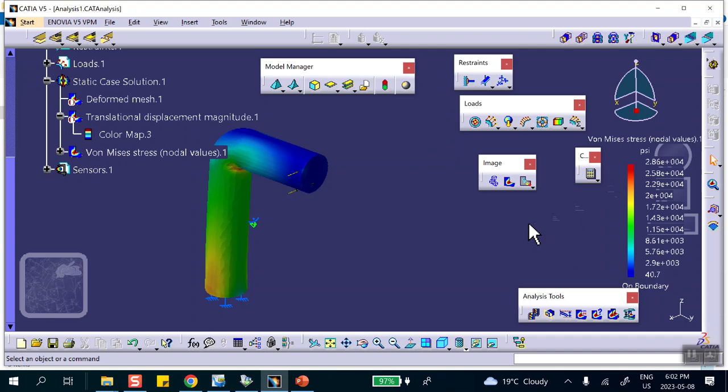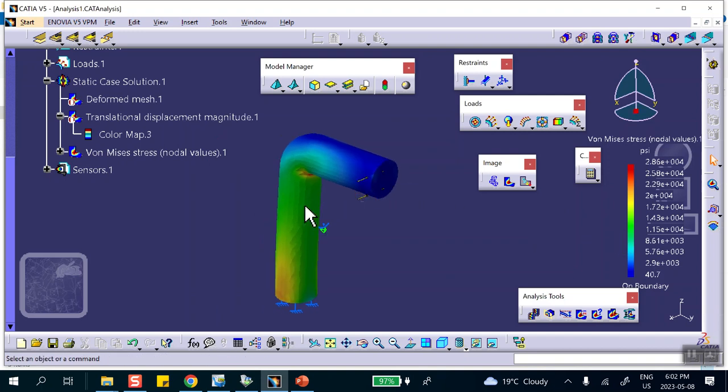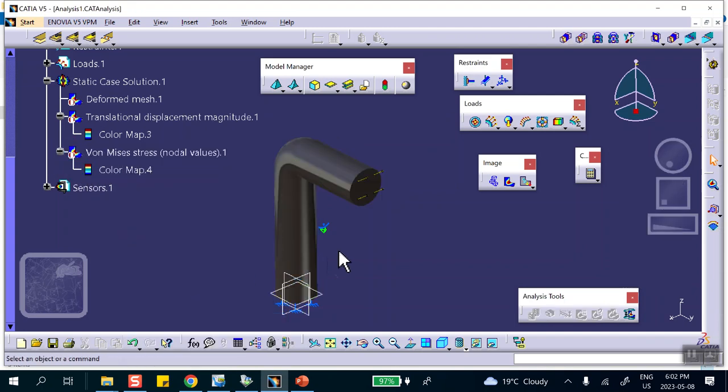This is why people have to do a mesh convergence study. In other words, it's easy to generate good-looking colors and numbers, but whether they are real or not is a different matter. That doesn't belong right now to this course, okay, right now. We'll talk about these things more in detail. Now, a couple other things. So let me deactivate. When we are done here, I can deactivate any of these plots that I have generated, like that, for example.